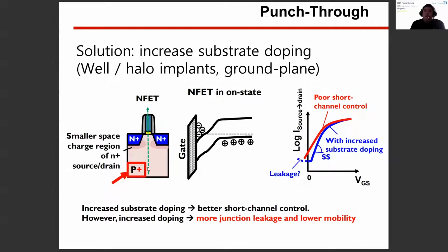If we put in more doping material than in normal devices, the depletion region gets shallower. However, the increased doping causes poorer mobility because the chance of scattering is higher than in normal devices. So this method is not widely used until now.